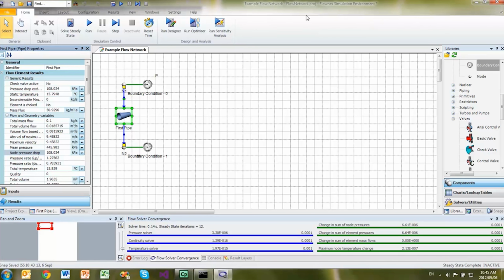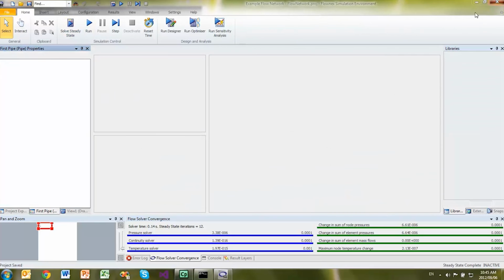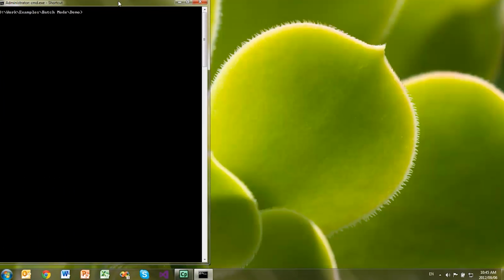So now I will quickly demonstrate how to do this from the command line, and typically how you would use this in batch modes. Just going to save this and close it. Now we will just pipe a value of 100 into that inputs text file. That text file can be modified in any means from different software. The easiest is just to demonstrate how to use it from the command line. So to pipe in there, we will use the following command.